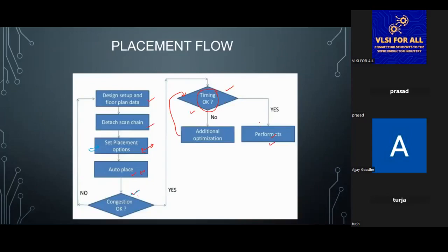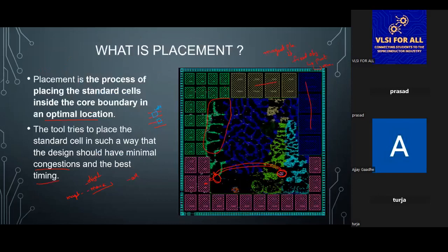If the congestion comes again, I can go back. Instead of this location, I can add blockages, partial blockage, or I can add padding also. I think you might know what padding is, right? Yes, sir. So that we can do. It depends on the particular location. For example, if I am getting congestion only for the cells, I can go for padding. If I am getting it in a region, I can go for partial blockage addition.